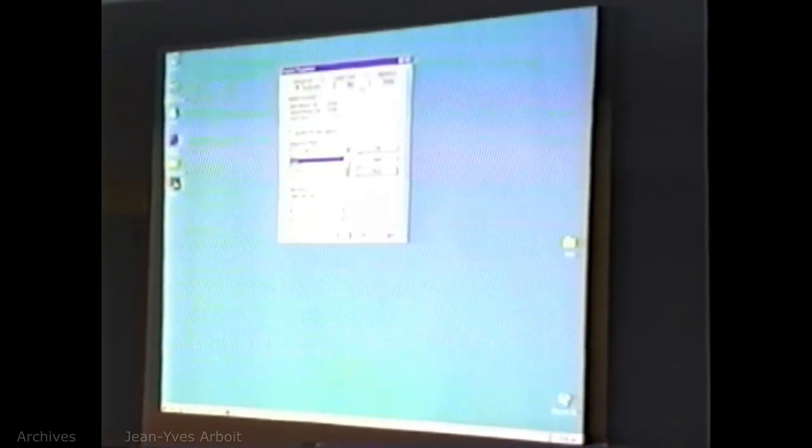The other one that I showed you guys, as far as the tabs go, was show window contents while dragging. Once again, turn that off. You'll increase your speed of Maya incredibly. Other things in here, your settings, so you can set your pixel rate and your refresh frequency inside here.